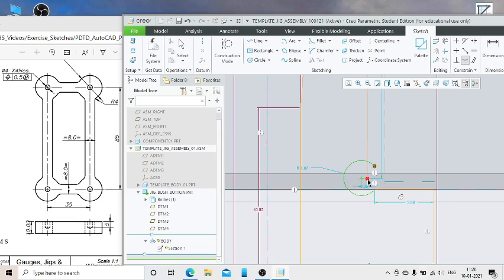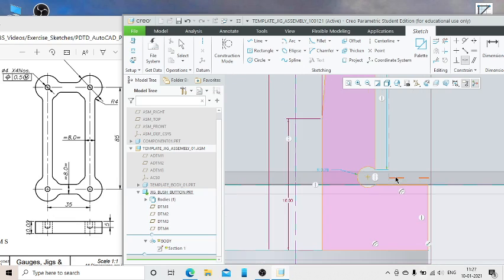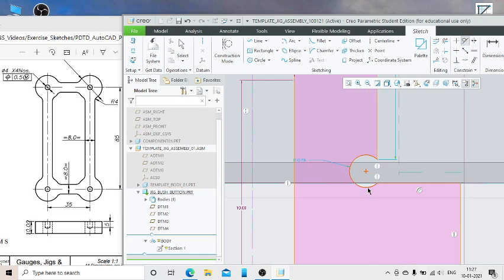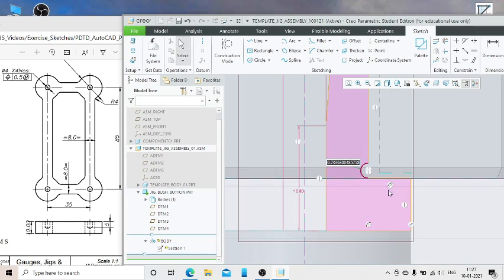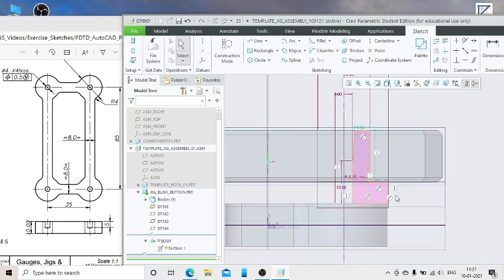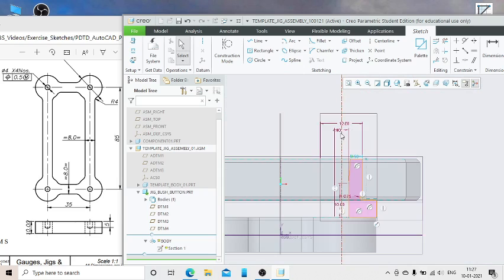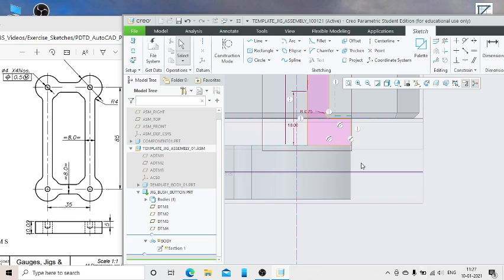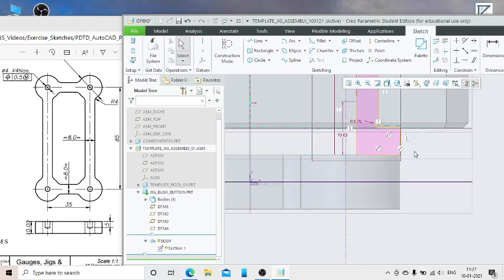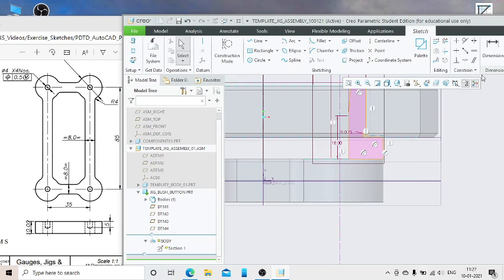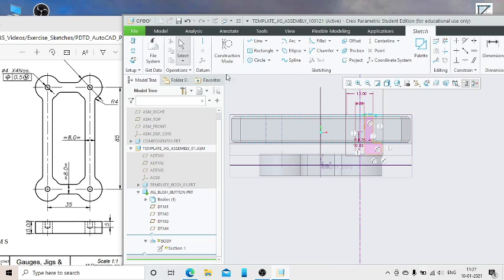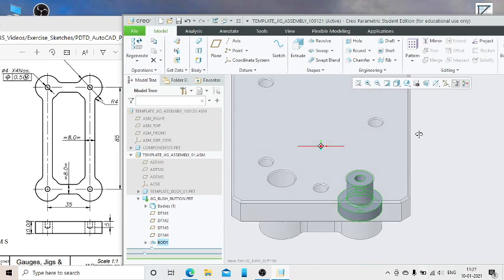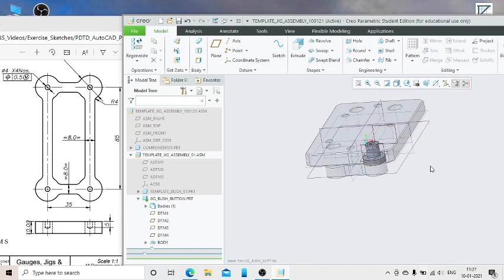Coincident here also we will make this coincident, and tangent, this we will make tangent. So this we will make 0.75. So this is 12 and this 4. We have made this. Then the outer dimension, I think it is not moving. So we can give a tick mark, so it is okay. Done.